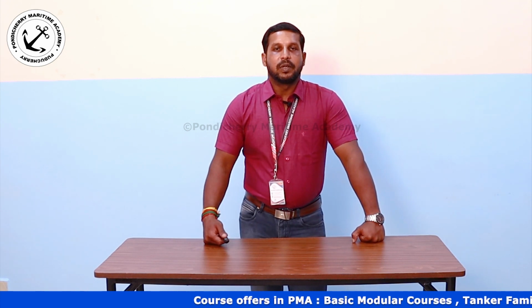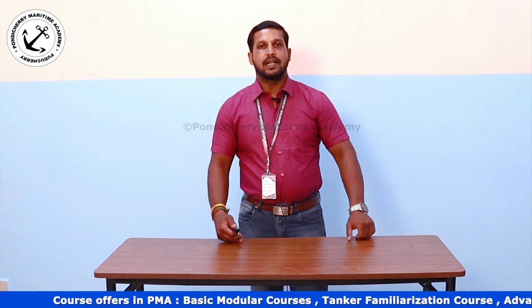So what are all the tests we do before we use these gas meters? The first thing, you have to make sure your equipment is serviced properly on an annual basis, and the second thing, your equipment is in good order and the sensors and the filter elements are all in good order. And the next one, you have to do a fresh air calibration to check whether your equipment is reading the values properly. And the next thing is the span gas calibration.